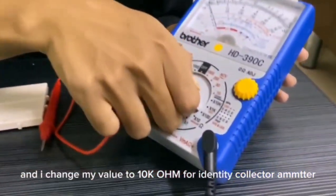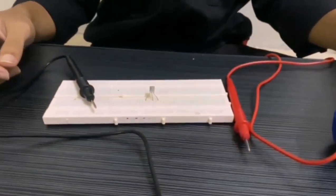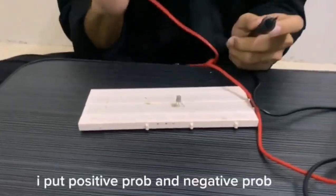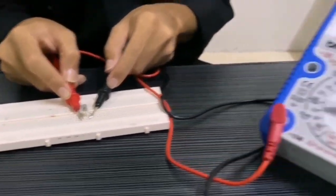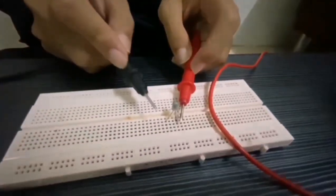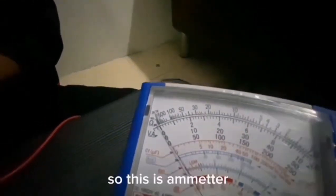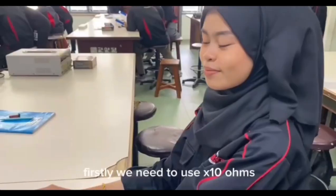And I change my range to 10,000 ohm meter to identify the collector and emitter. I assume the right terminal is the collector. I put the positive probe and negative probe, and the value is infinity. When I change the probes, the value is still infinity. So this is the emitter. That's all.